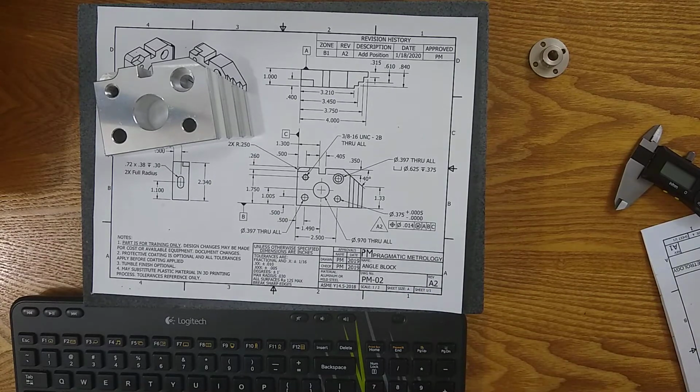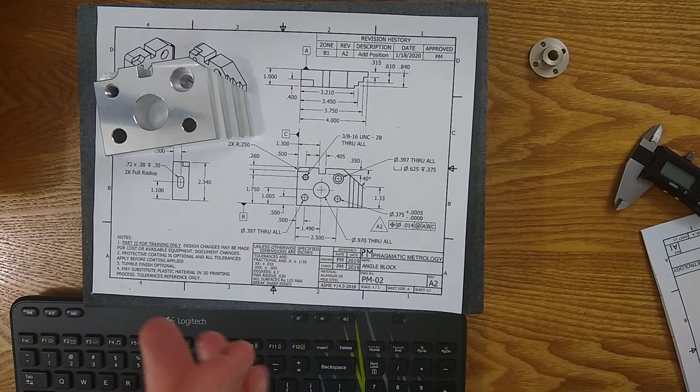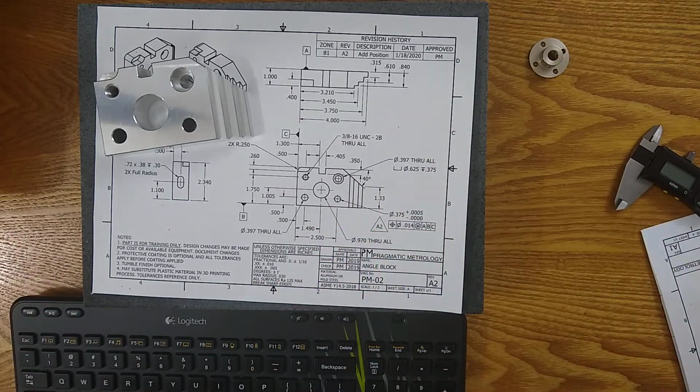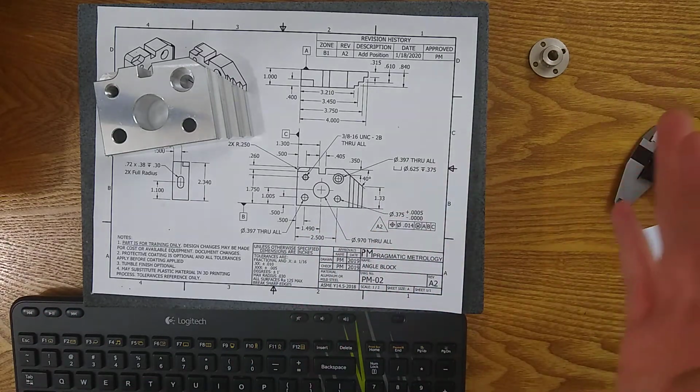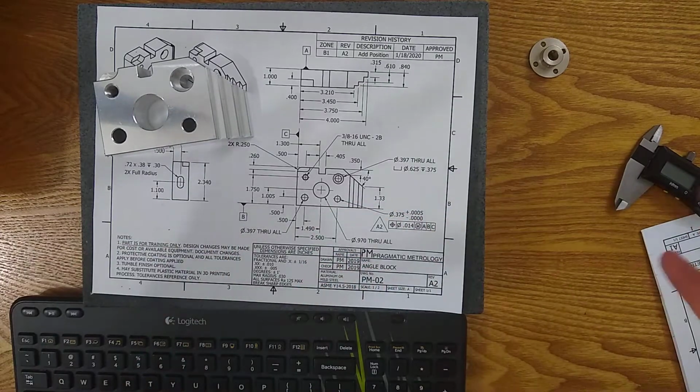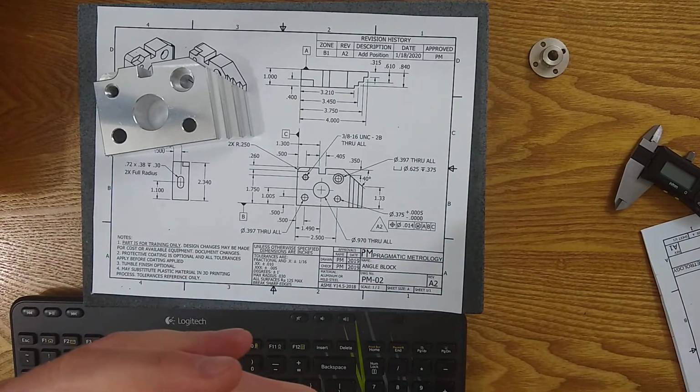So next up, unilateral tolerances. A lot of tolerances you see are going to be one direction instead of both. A bilateral tolerance is like plus or minus: plus 1 and minus 1, plus 5, minus 5. Sometimes you're only allowed one direction. The convention is usually involved in assembly to guarantee clearances.